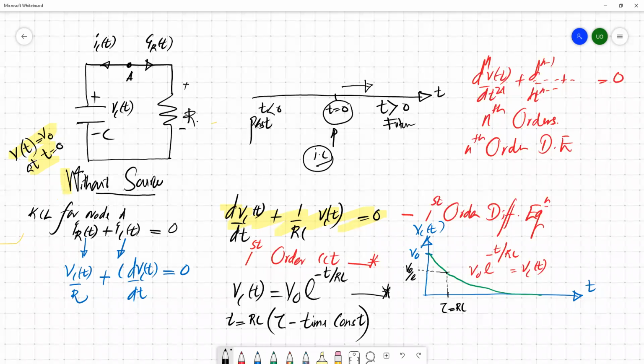If it is an RC circuit, the product of R and C gives the time constant of the circuit. If you know the time constant, for example if it is very small, the behavior of the capacitor is something like this. This time constant is somewhere around here, so it can immediately discharge.